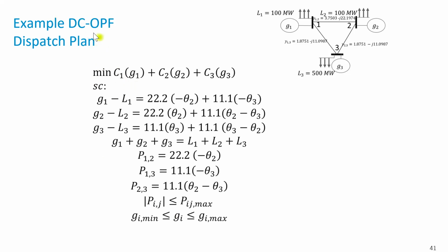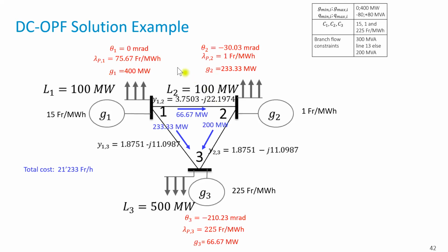That means what I have approximated are the constraints of the grid. And because my cost is linear, my constraints are linear. This is a linear optimization problem, called a linear program. So within this context, assuming this approximation, those are the approximated marginal costs. If the DC approximation were correct, it would not be an approximation, but the true thing here.